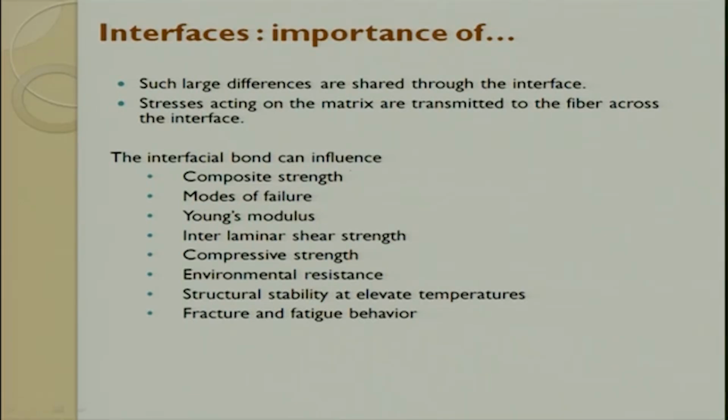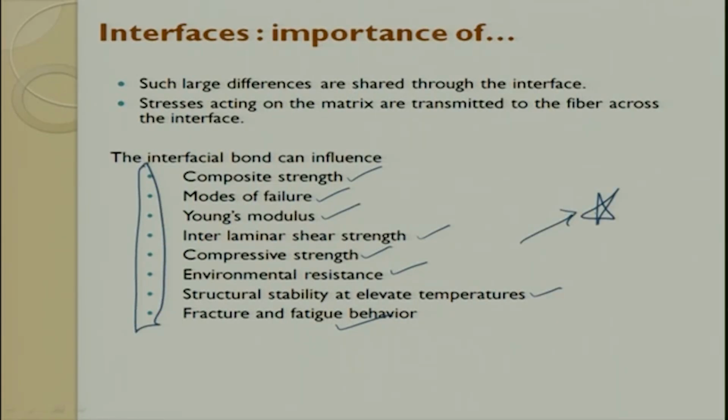So the interface can influence the composite strength, modes of failure, Young's modulus, interlaminar shear stress, compressive strength, environmental resistance, sustainability at higher temperatures, and fracture and fatigue behavior. These are all important properties for the interface. Very, very important for the interface in ceramic matrix composites.